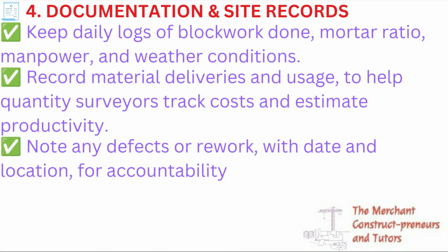Then the curing, you also cure and clean all the joints, ensure that everything is neat the way it's supposed to be. So the next thing on your checklist is documentation. You need to keep daily logs of block work done, mortar ratio, manpower and weather conditions. These are very important, because without this you will not be able to track whether the number of blocks that was supplied was actually used, or they used more than what is supposed to be. You need to check that.